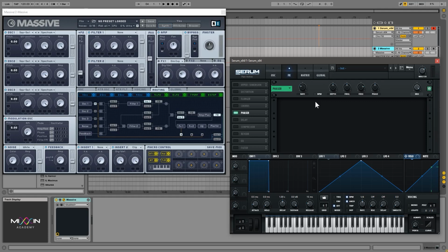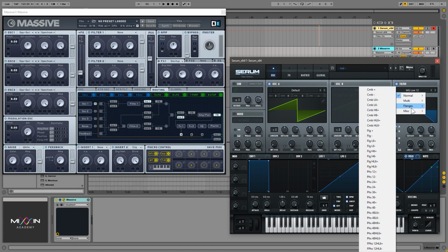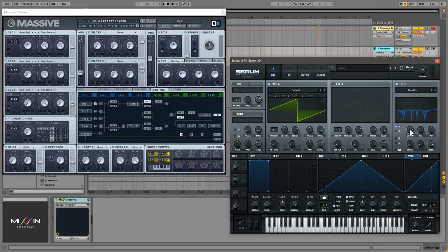They actually change the phase of the signal in a certain spectrum position. So in a certain frequency spectrum position, they change the phase, hence you get that notch effect of several notches being introduced to the signal, like the one we saw right here in these special effects, like this phaser filter. And it sounds like a phaser by creating those notches artificially.